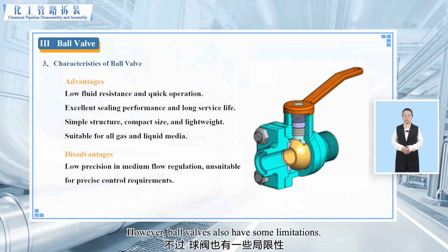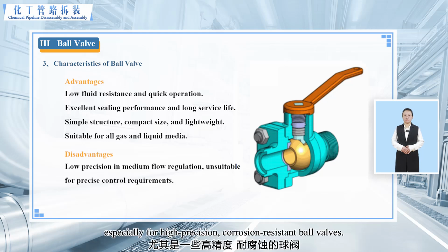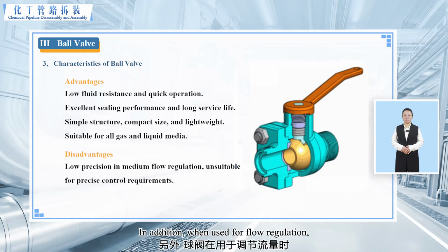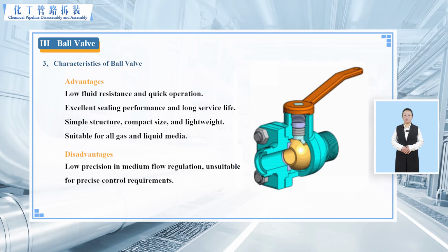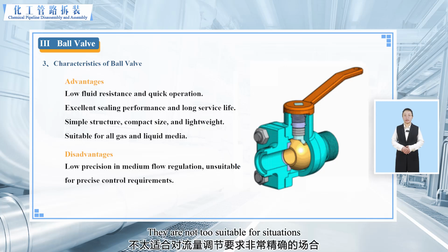However, ball valves also have some limitations. Their manufacturing cost is relatively high, especially for high-precision, corrosion-resistant ball valves. In addition, when used for flow regulation, their precision is relatively low. They are not very suitable for situations requiring very precise flow regulation.